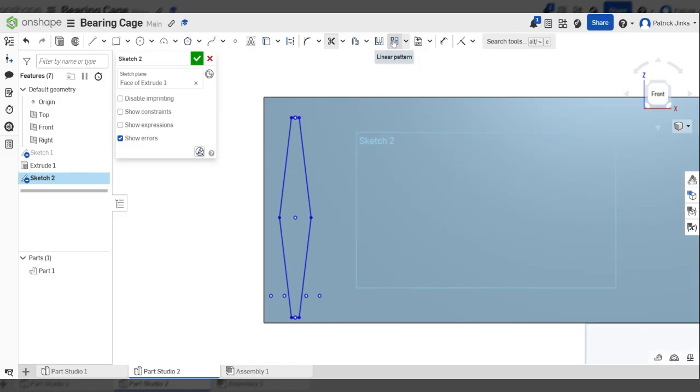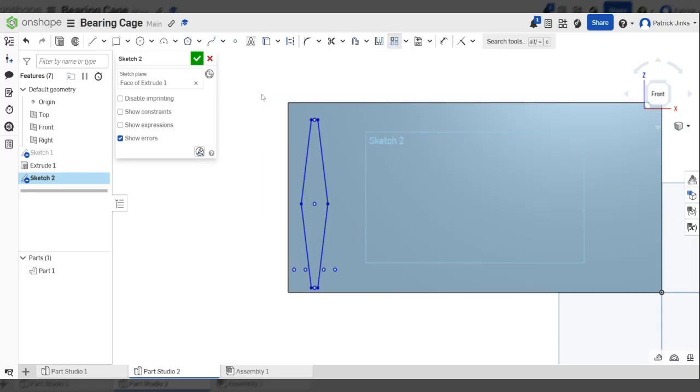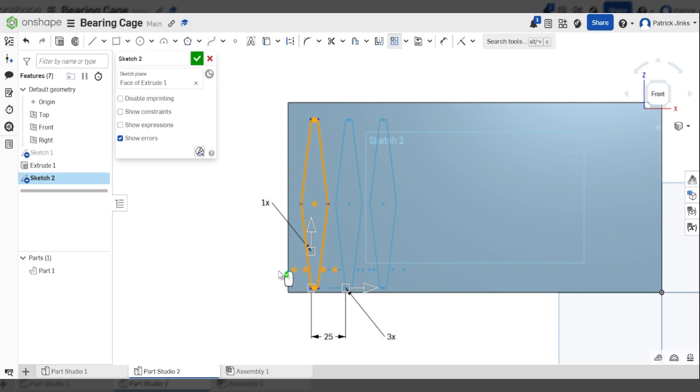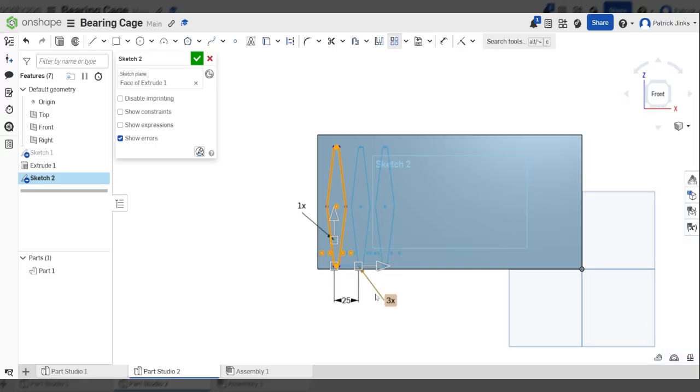But you're going to click the linear pattern tool in the sketch menu, select everything you've got. And now the only difference here is, and I think this makes it a lot easier, which is why I prefer to repeat the sketch rather than the feature, I've got these handlebars. So I can just pull it out, see whereabouts looks good. I've got my number there. I can just double click like a dimension. I can double click it. I want 10 of these.